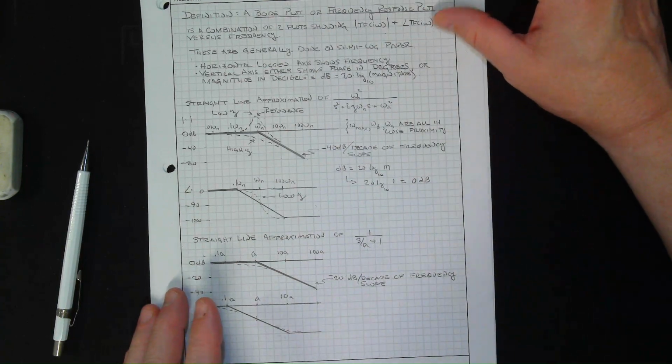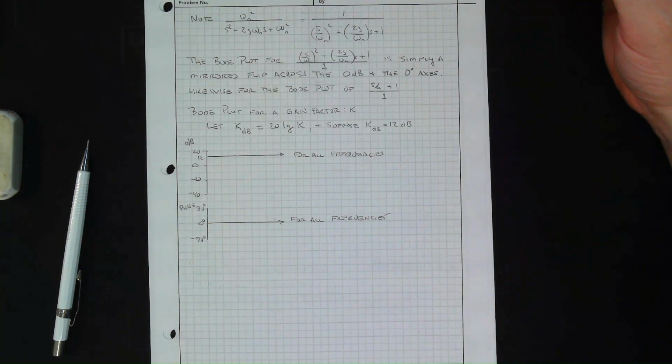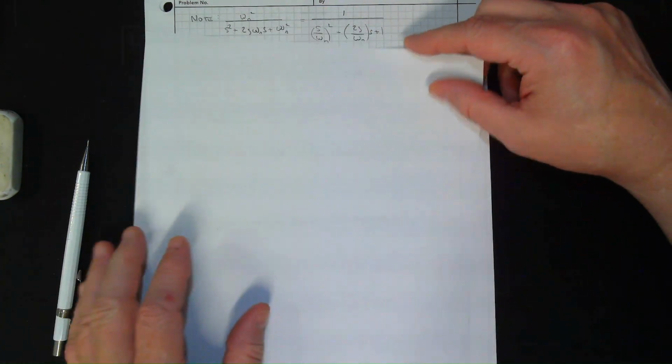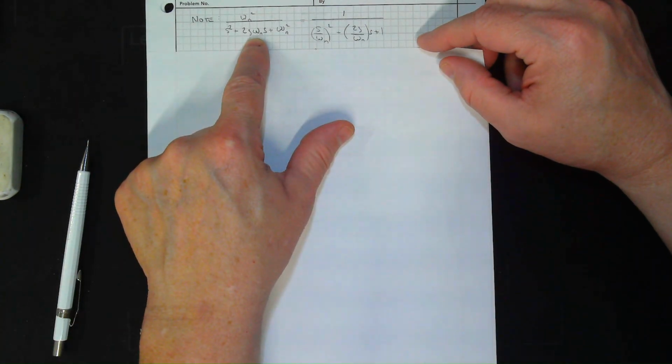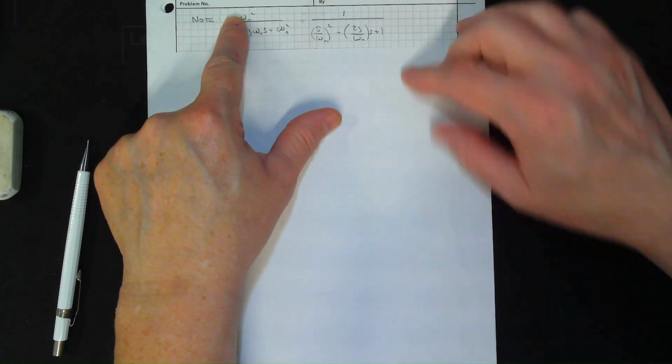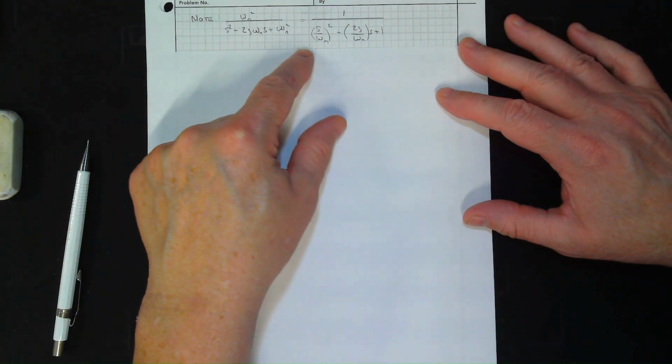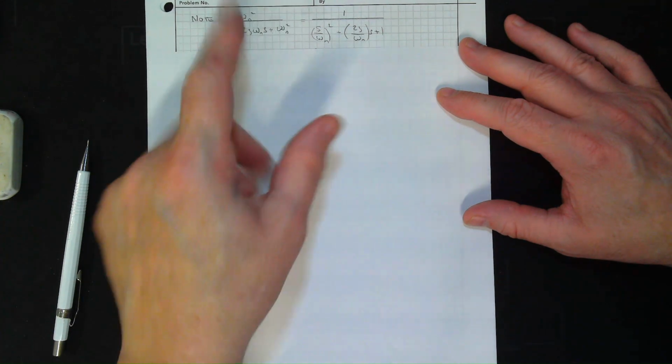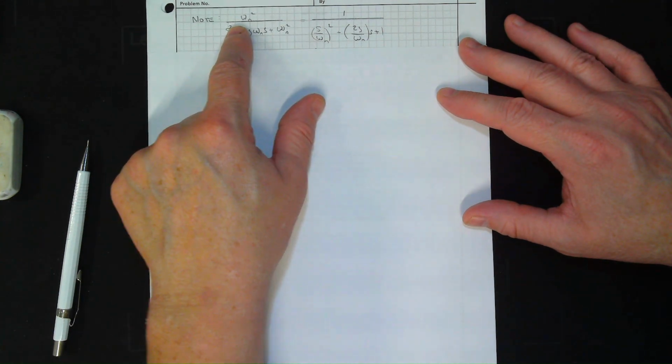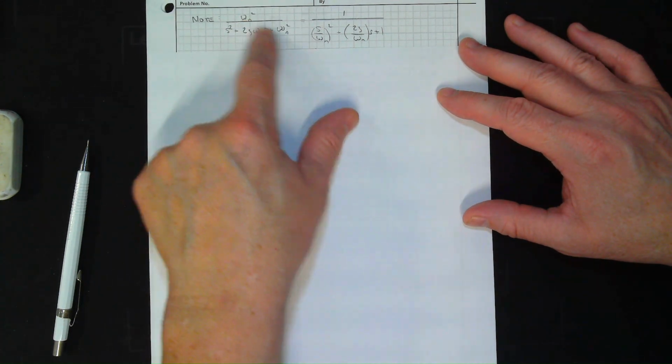Let's take this just a little bit further in this video. So we saw what this one does. By the way, we can put this in classical unity static gain form. If you let s go to 0, you get a 1. But people will often write it in this form. So divide by omega n squared, and we still have unity static gain.